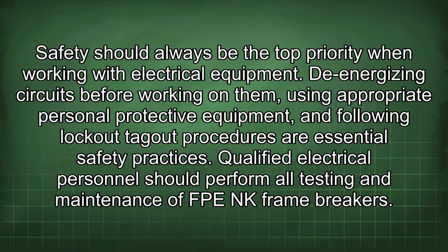Safety should always be the top priority when working with electrical equipment. De-energizing circuits before working on them, using appropriate personal protective equipment, and following lockout-tagout procedures are essential safety practices. Qualified electrical personnel should perform all testing and maintenance of FPE NK frame breakers.